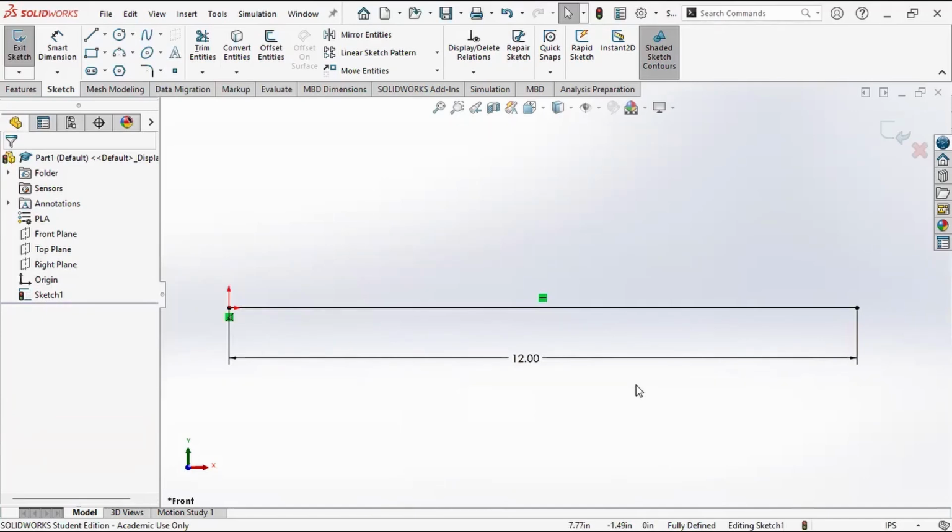And that's going to be a key feature with some of your upcoming exams and project: for these starter parts anyway, we expect fully constrained sketches. I expect to be able to open these sketches and see everything that you've drawn in here to be black. That means it's fully defined, it's locked down. I can't get in here and accidentally drag it around and mess up the part in the future. So that is sort of the basics of constraints.